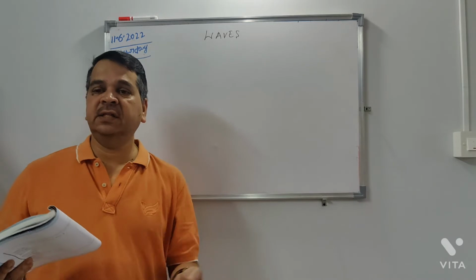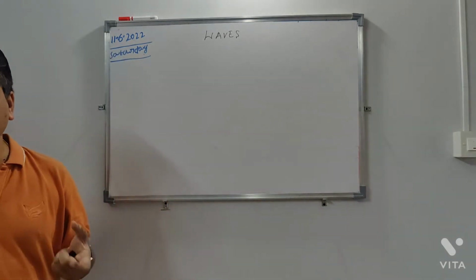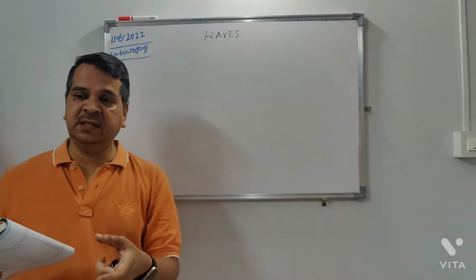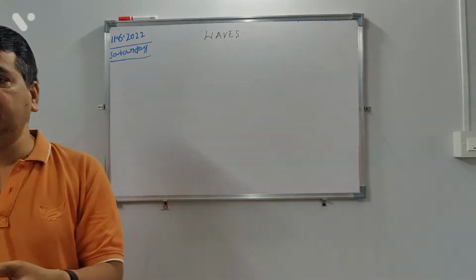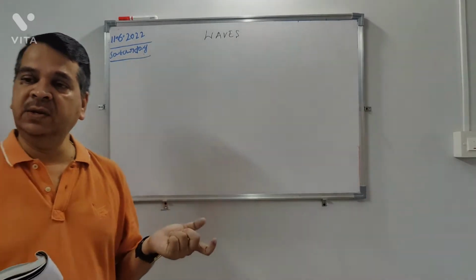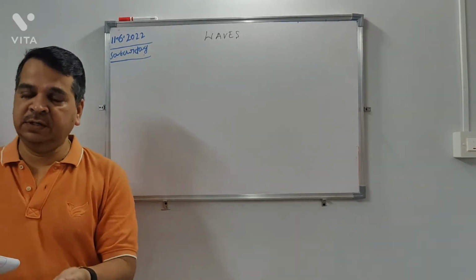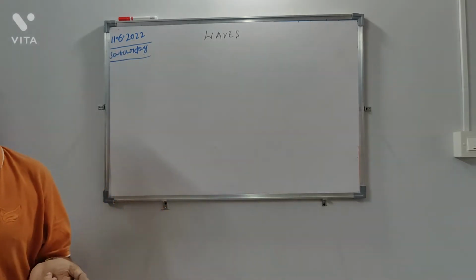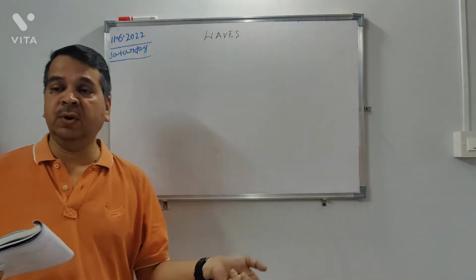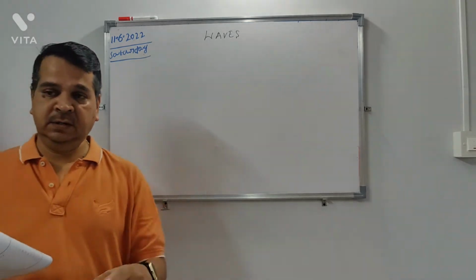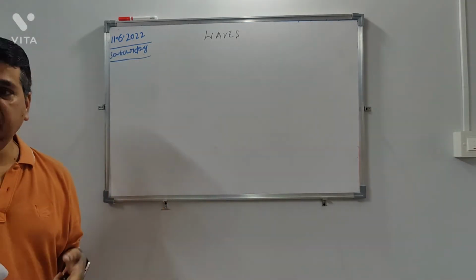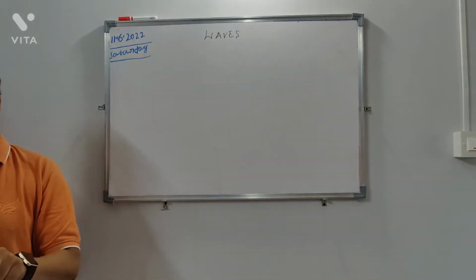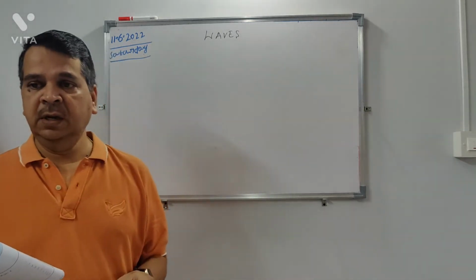Okay. So in general, there are monoatomic gases, diatomic gases, triatomic. For diatomic gases, Cp by Cv is equal to 1.4. So normally we will use 1.4 because air consists of mostly nitrogen. So nitrogen is diatomic, that's why we are using it. For monoatomic, gamma will be different. I have studied that in kinetic theory. Diatomic and triatomic gamma will be different, but we will be using the diatomic one.